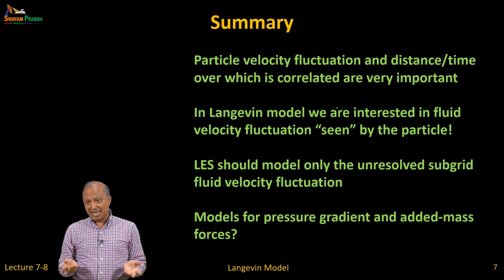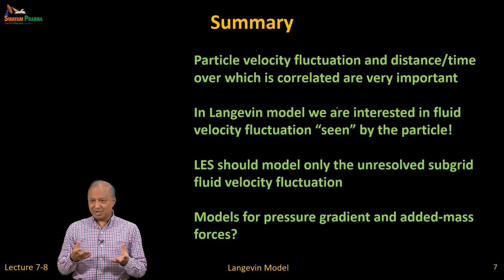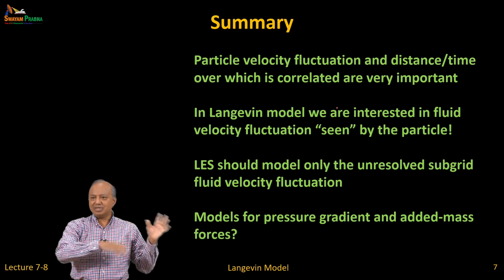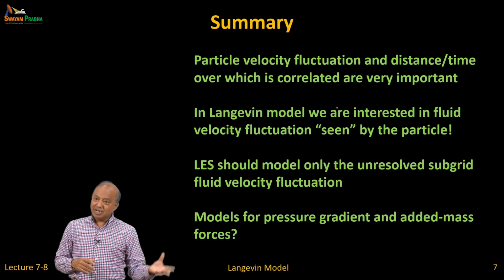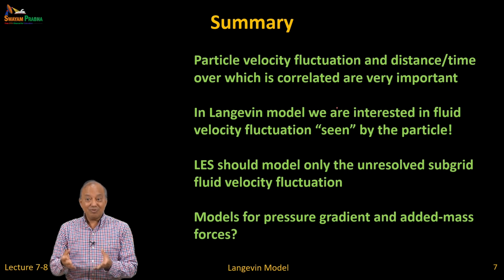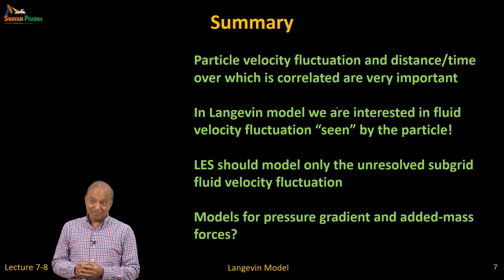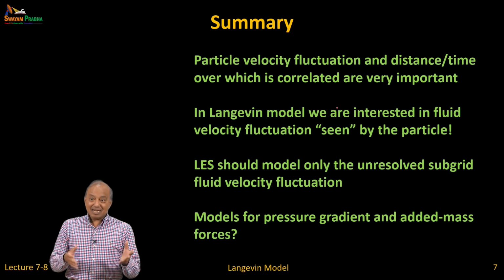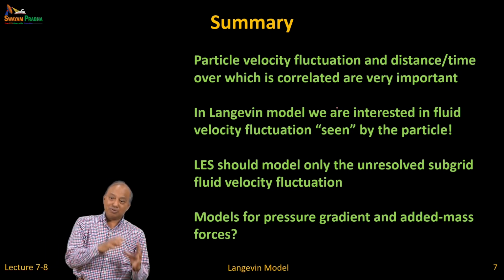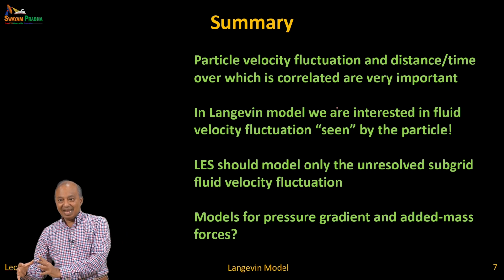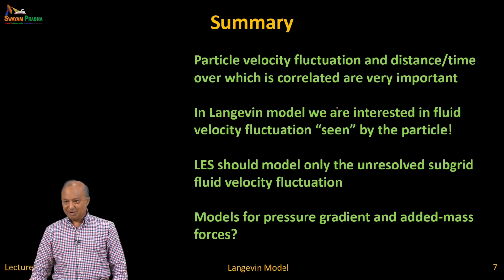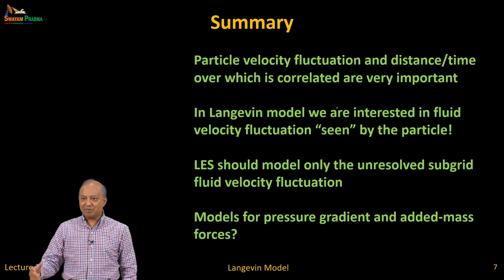So we did an LES, because that room was too big for DNS, and we calculated the dynamics of droplets. And we did a RANS where the flow was steady and we put particles, but then we had to put in this Langevin model. We put the Langevin model and compared the distribution of droplets that you compute with RANS against LES. The RANS was about 5 to 10 times cheaper, in that particular problem.